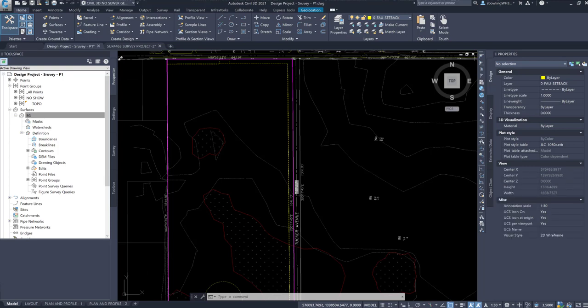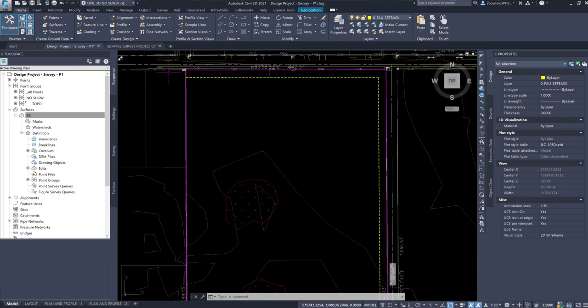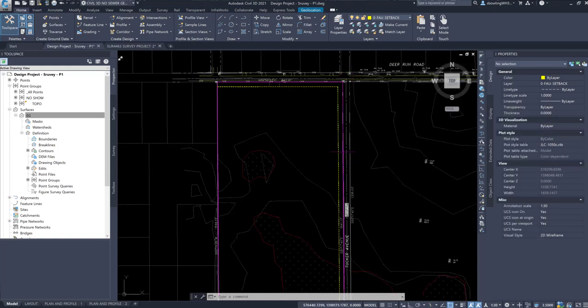I would suggest tying in Tucker Avenue, and maybe you go ahead and build access, do an intersection over here, so you're sharing an access point over here, but you'd have to get access easements from this property owner, or you build the road down here and just access the site this direction. Maybe put a road through the back of lots here and you tie it back in. That would actually probably be the most usefulness of your site. But we'll go ahead and have a minimum lot width and a minimum depth. All right, that's it for this video.